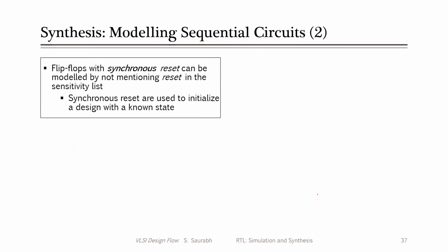Sir, from the perspective of the Verilog code or any, functionality? No, just functionality. Not from the Verilog perspective, just tell me the difference between a synchronous reset flip-flop and an asynchronous reset flip-flop. Okay, sir, asynchronous reset occurs even if the reset is triggered. The reset signal changes even if there is no positive or negative edge of the clock. But synchronous will only happen if there is clock triggering.